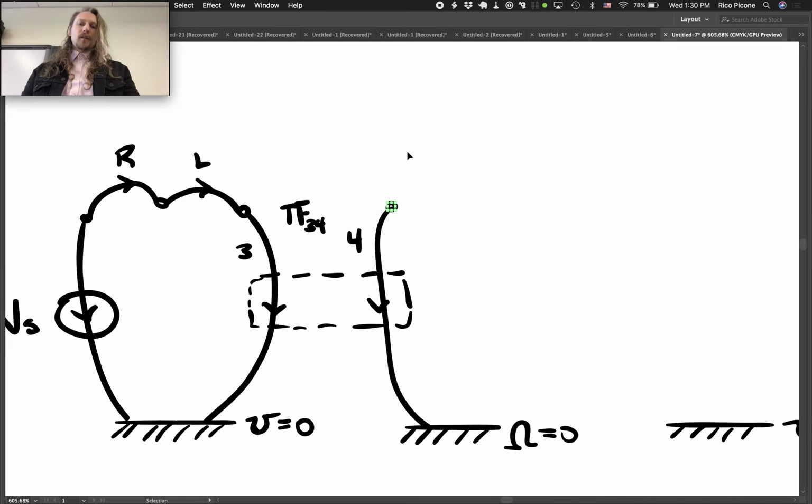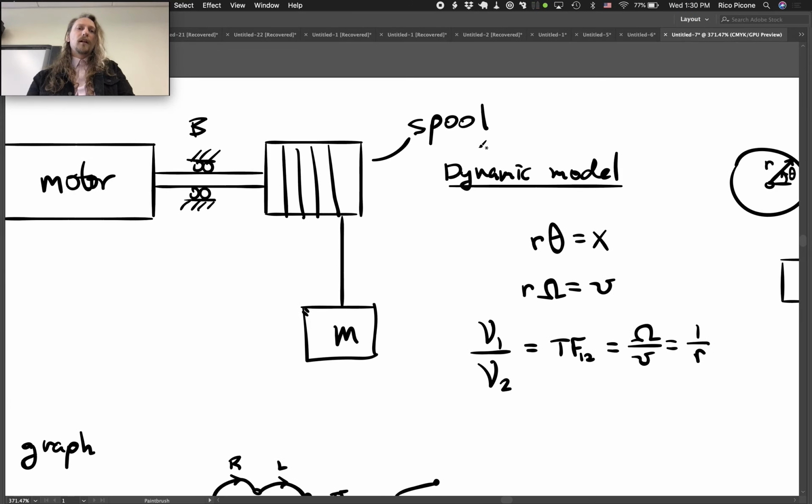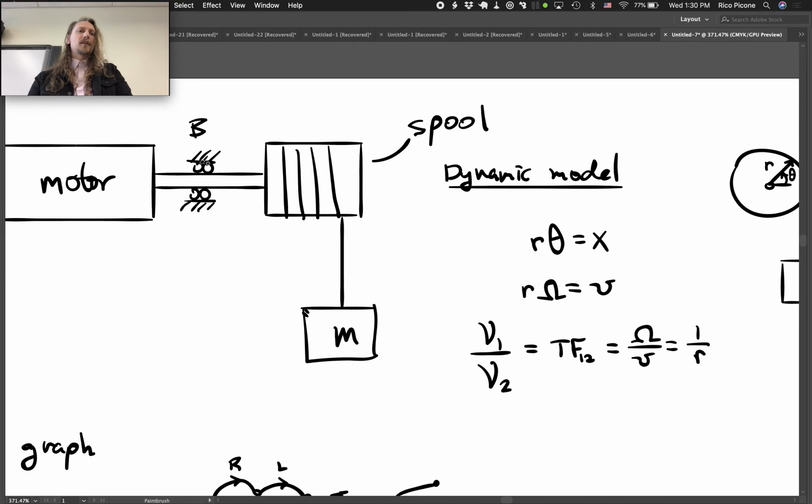And this rotational side here has got a few things going on. It's got that interaction through the motor. Its shaft, though, has some bearing damping on it. We've got the external bearing, which is on the same shaft. We'll assume this shaft is relatively short and stout, so it doesn't have a lot of twist in it.